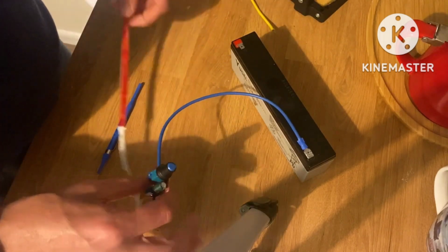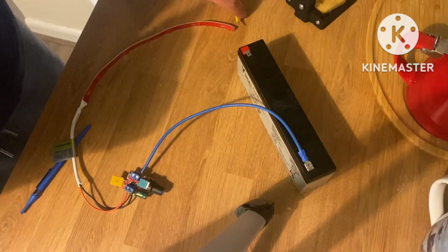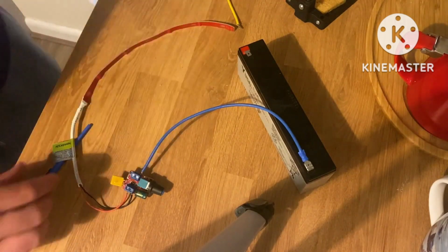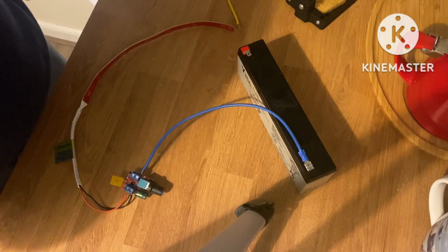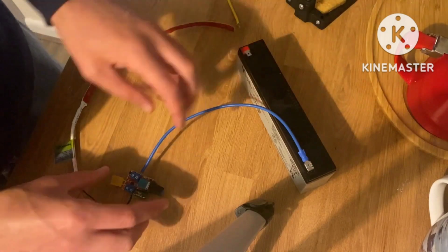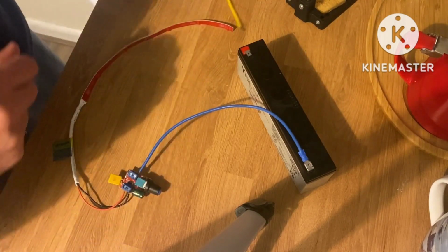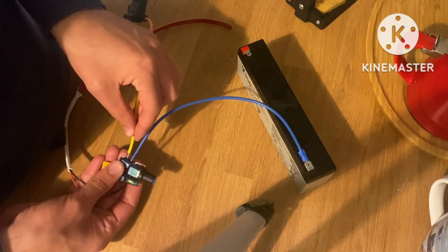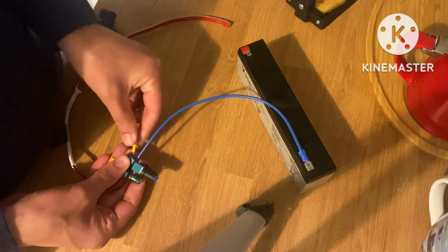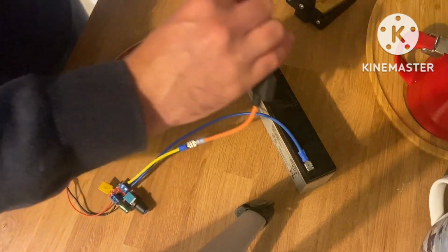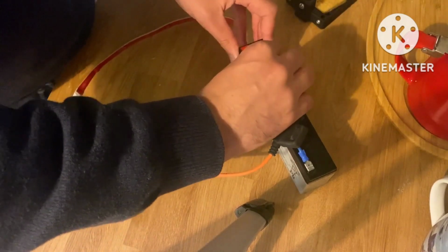So far, so simple. Now, at this point, I'm just going to turn everything on and use my PWM generator just to prove to you that this does work at this stage. So what I've done is I've connected a 0 volt line up to the 0 volt input on my PWM generator. Then I'm going to do the same thing with a plus volts lead. So that goes into the plus volts input of my PWM generator. And then when I connect the battery up, nothing will happen because the PWM generator is not turned on.